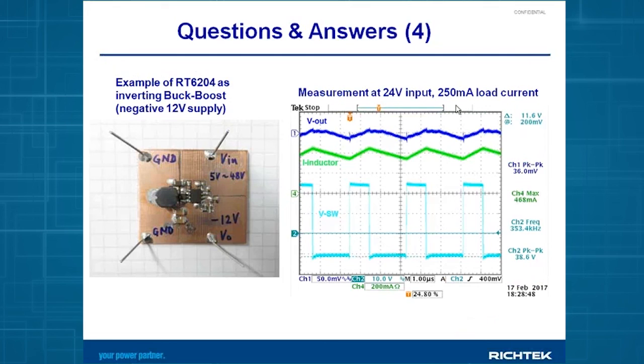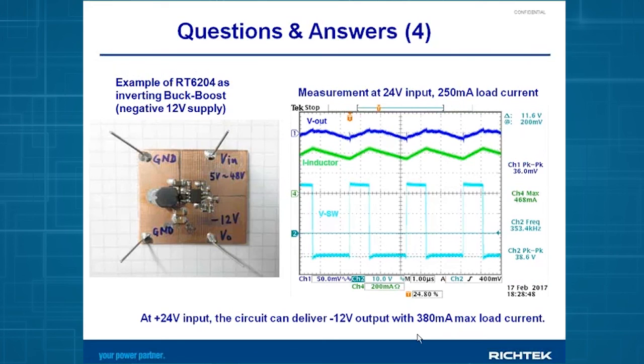So you see that this application is not able to deliver the full load current of the IC rated load. Actually, this application can only reach around 380 milliamps maximum load condition. And this output load is input voltage dependent. So I hope this was interesting for you.